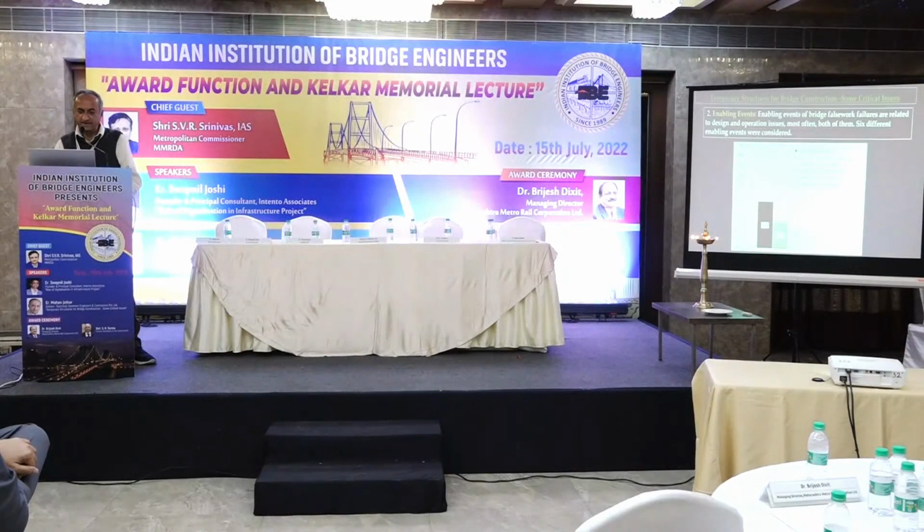Then we come to enabling events, which are related to design and operational issues, and mostly both of them occur at the same time. 6 different enabling events were considered. Again, unknown causes predominate the overall analysis. Then design related issues of say 26%. Inadequate bracing, this is the single most reason for many failures. That is, the falsework is not braced adequately.